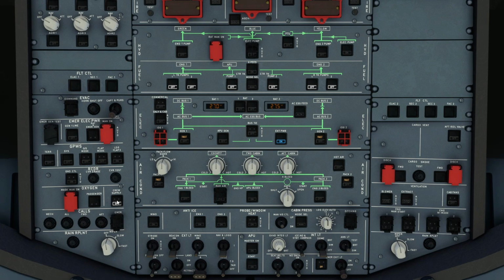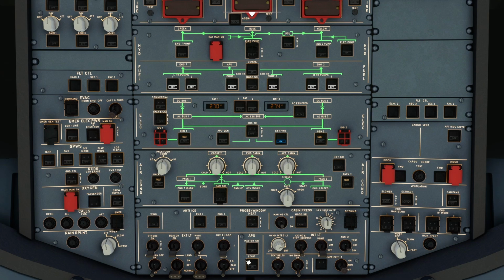Okay, external power is on. We can go ahead and turn on the crew oxygen supply. Set the ADIRS 1, 2 and 3 to NAV. It sets up some of the lighting, so we'll turn on the overhead integral lights, nice and bright for the overhead panel. We'll arm emergency exit lights. Nav and logo lights can go on. Strobe lights can be set to auto.